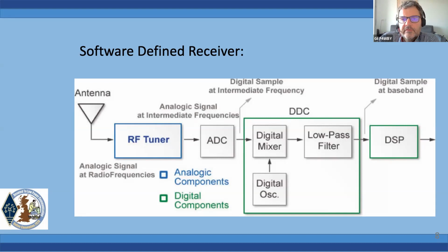And what you want is a big difference between the signal you're receiving and the floor of the noise, because that's what's going to allow you to actually make sense of or decode the signal, or if it's Morse code or SSB, that's going to allow you to basically hear what's going on and be able to make contact. So what software-defined radios do really well is lower the floor level, and that's a big advantage, and quite an increase in performance actually.